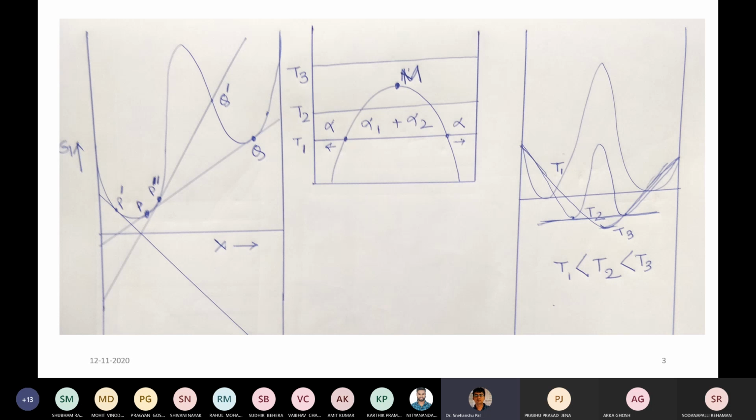There is a different way you can represent the phase diagram, and in reality those kinds of phase diagrams are available mostly, where you cannot get the two equilibrium points on the same horizontal axis parallel to the x-axis. It may have ups and downs, so you can draw a common tangent, and also you can get the equilibrium phases.